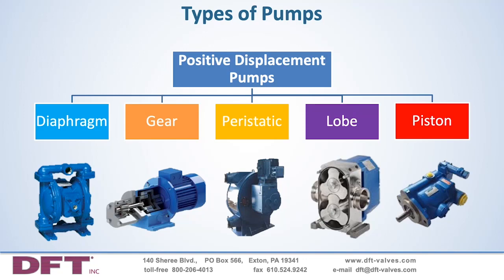Lots and lots of these slugs moving forward creates a continuous flow, but the pressure profile for this type of pump is a bit more choppy, and small pulses of pressure exist. Move far enough away from the pump and you see less and less of that pulsing in the pressure profile, but close to it, where the check valve lives, you'll see a more pulsing nature to the pressure profile.